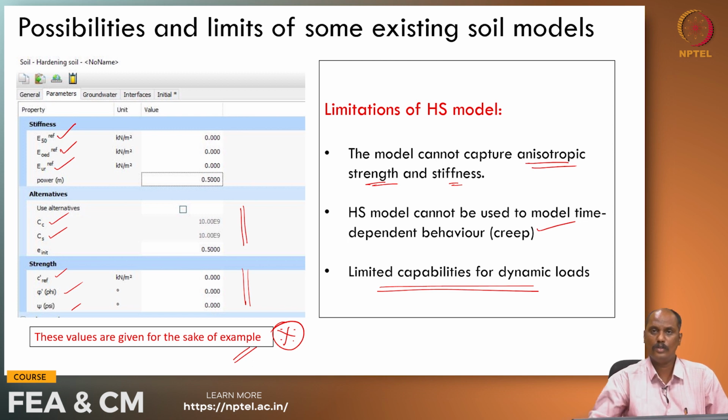So, it is up to the discretion of the designer or the user to understand the real stress strain relationship of the soil which he or she would like to model or analyze, and based on the available framework, intelligently choose the soil model before trying to capture the real behavior of soils.